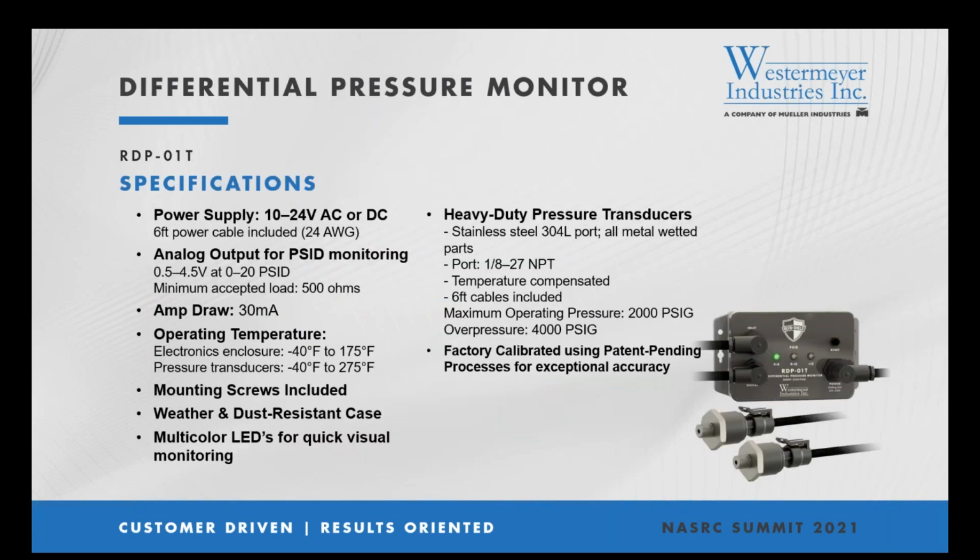So here are a few key features that I'd like to note. This product requires a power supply of 10 to 24 volts AC or DC. It provides an analog output of 0.5 to 4.5 volts, which is a range of 0 to 20 psid. There's also, as I indicated, a visual indication on the front with multicolored LEDs.